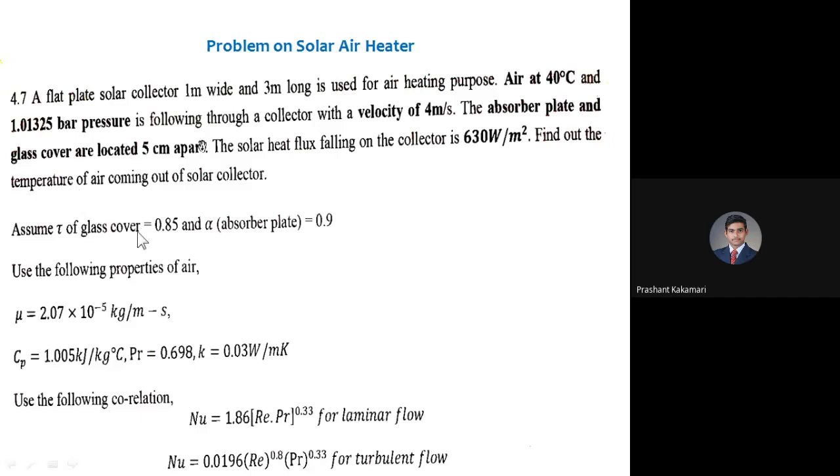So if it is a fluid, I can consider the heat transfer coefficient h between the fluid and the plate. Delta T I can consider as the inlet and outlet temperature difference. A is the cross-section area, or sorry, the surface area of the plate, or the cross-section area of the plate, how much it is in contact with the air. That area you can consider, and one can find out the h value if you know the Q value.